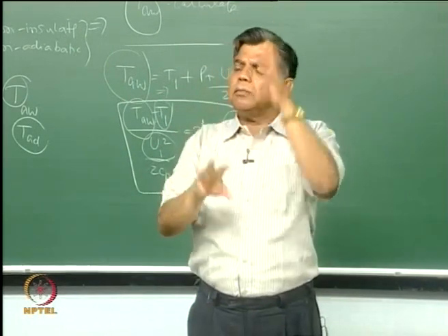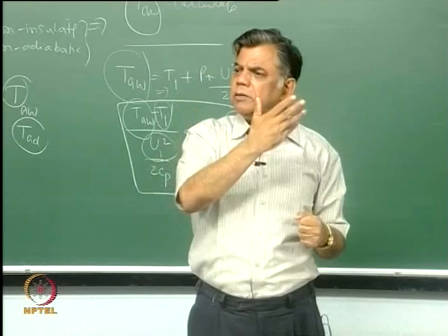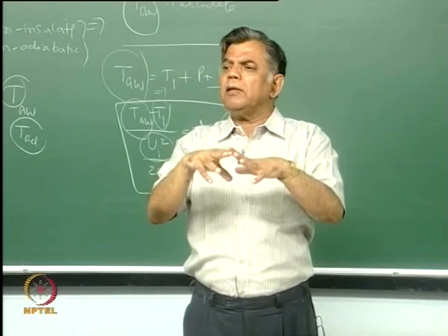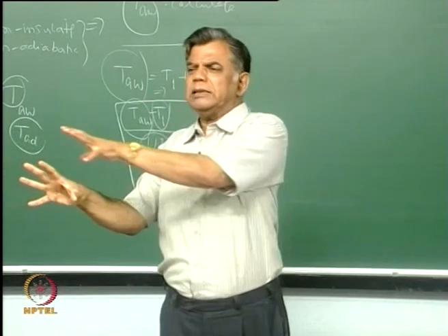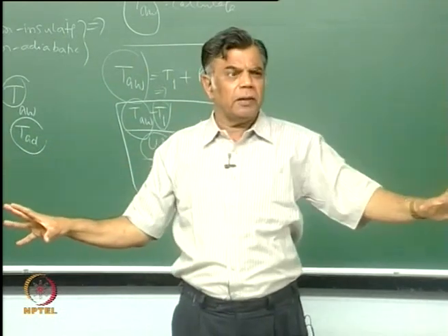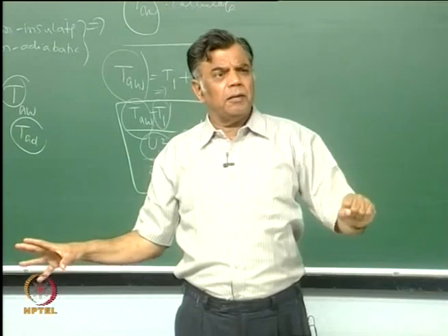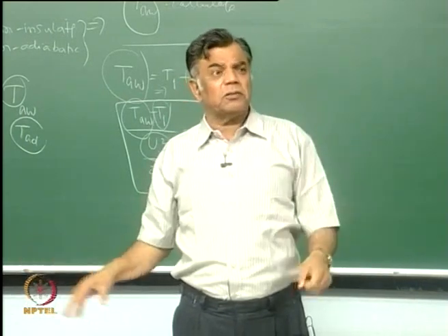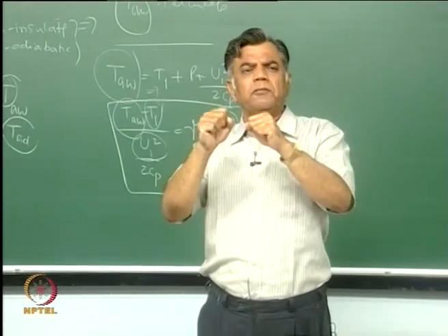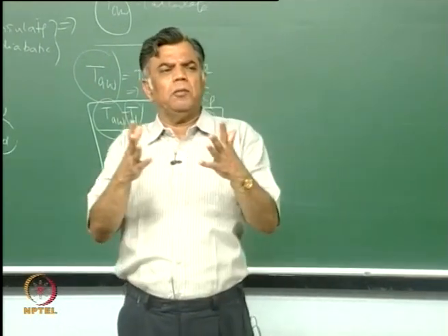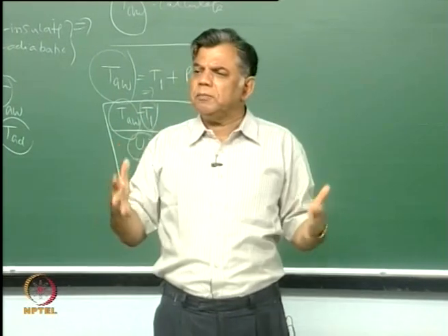Then when the temperature profiles were done, you got the heat reversal. Then you go to the adiabatic wall temperature. There you find you can get an adiabatic wall temperature expression, but that is exactly what appears in the non-adiabatic case. Therefore, in the non-adiabatic case, even to calculate the heat transfer, first calculate the adiabatic wall temperature. That can be obtained through the definition of a recovery factor, which is nothing but (T_aw - T1) by U1 square by 2 Cp.